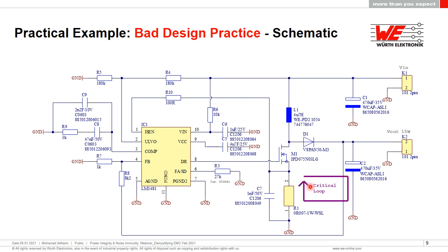That's quite clear. I'll just draw your attention to a couple of things as we look at the schematic, just to identify some of the things that may come out straight away in terms of an issue, or let's say a bad design practice. The use of aluminium electrolytic capacitors on the input and the output without any other type of capacitor also being present. So that's an initial point to keep in the back of the mind. We will talk about capacitors in quite a bit more detail later on, but this is not necessarily the best design practice that we should be implementing.